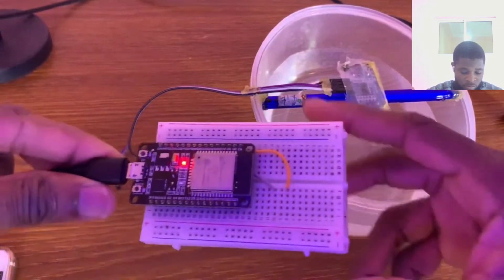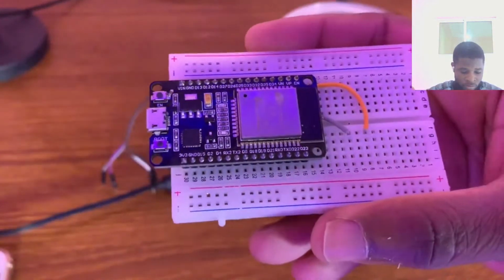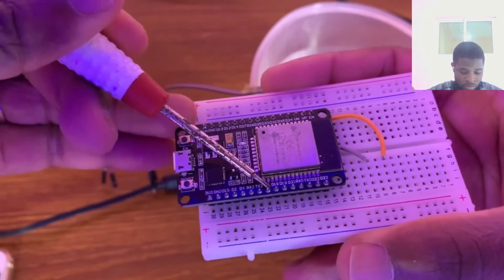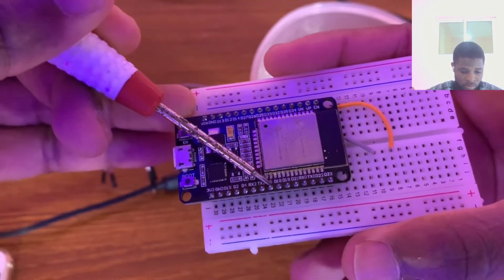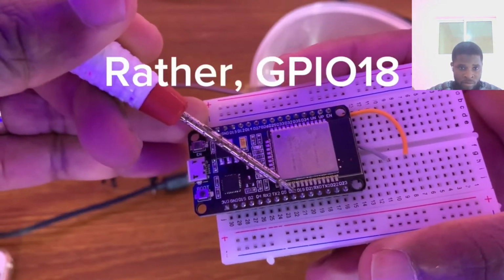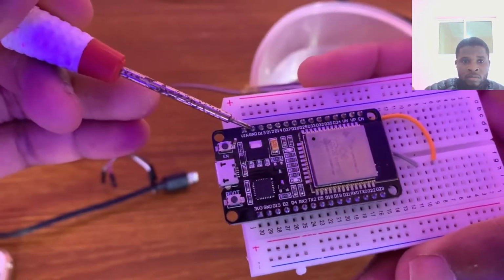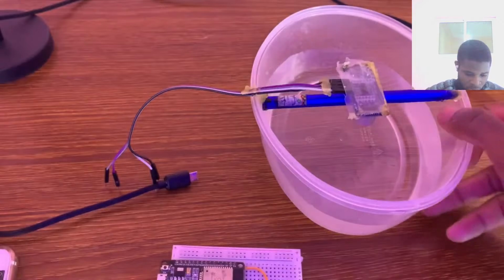I need the ESP32 board, and GPIO 5 is attached to the trigger pin, and the echo pin to GPIO 15. So the VCC to the in, and the ground of the sensor to ground.